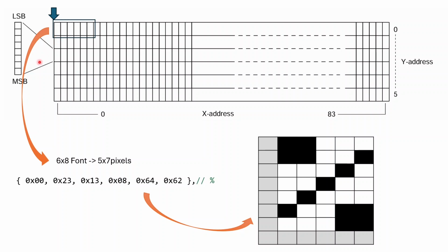The frame buffer also has, let's say, a pointer that is formed with a combination of the X address and the Y address, and in this way you can manipulate the address at which the data lands. In the current example, you see that this pointer is at this location. That means X address is 0 and Y address is 0.